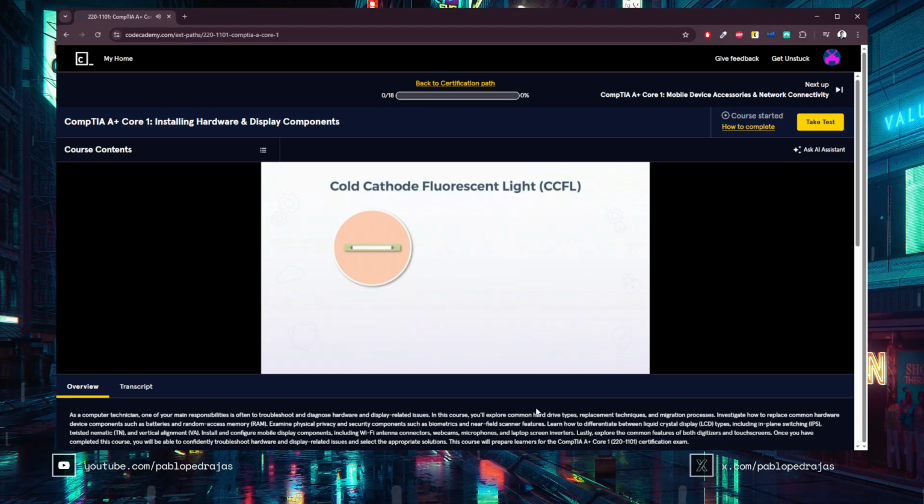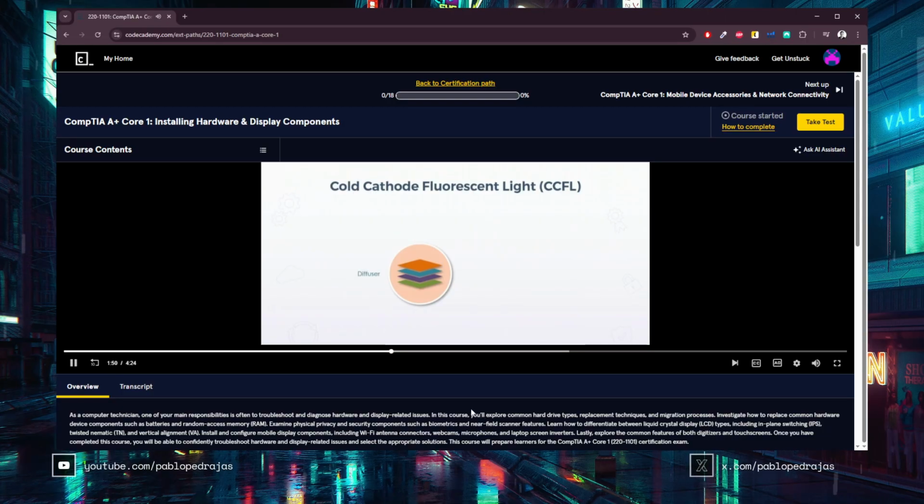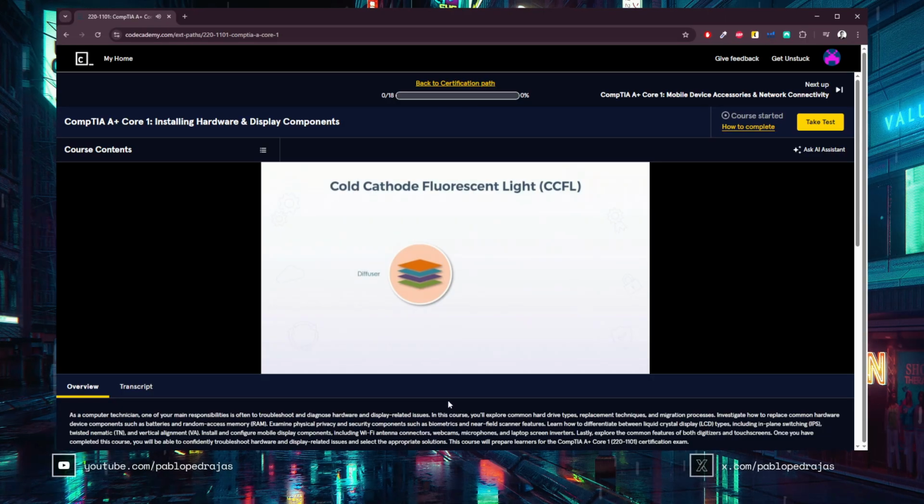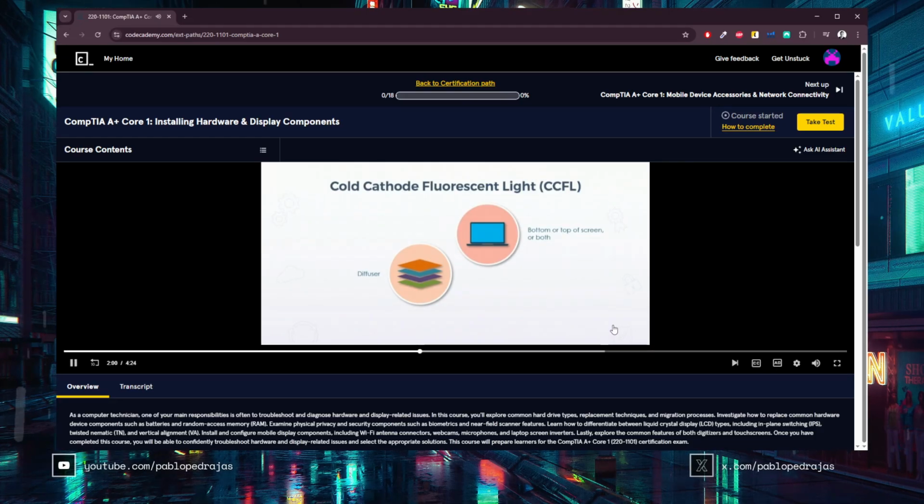As for the light itself, as mentioned earlier, it's essentially just a greatly scaled down version of fluorescent lighting, typically implemented as a small tube, which is able to provide adequate lighting while not raising the ambient temperature too much, which helps to prevent overheating and subsequent damage to other components. Now, depending on the size of the screen, smaller units could usually get by with just a single CCFL in conjunction with a diffuser to help spread the light out more evenly. And the CCFL itself is typically located in either the bottom or the top of the screen itself, possibly both in larger screens, with some of the largest models possibly having more than two. Maybe there would be one located on either side as well.